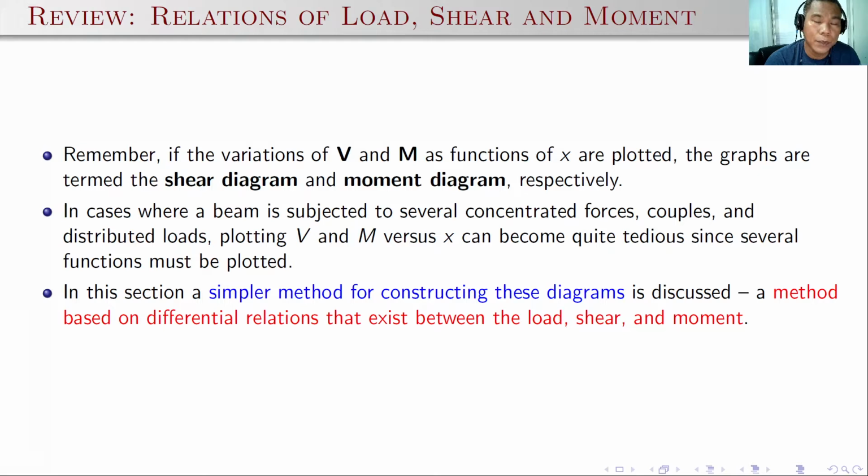In cases where a beam is subjected to several concentrated forces, couples and distributed loads, plotting the shear and moment versus x can become quite tedious since several functions must be plotted. Of course, there is a simpler method for constructing these two diagrams, as we will discuss here. A method based on differential relations that exist between load, shear, and moment.